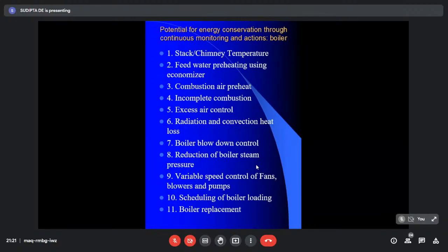Okay. So point 9 is basically related to the auxiliary power. Auxiliary power consumption means when you have to run a device, then several devices are attached to that, which also consume power. So the auxiliary power consumption at low load decreases if we can make a variable speed drive, because variable means at a lower speed, if you can run that system, then it will consume less electricity.